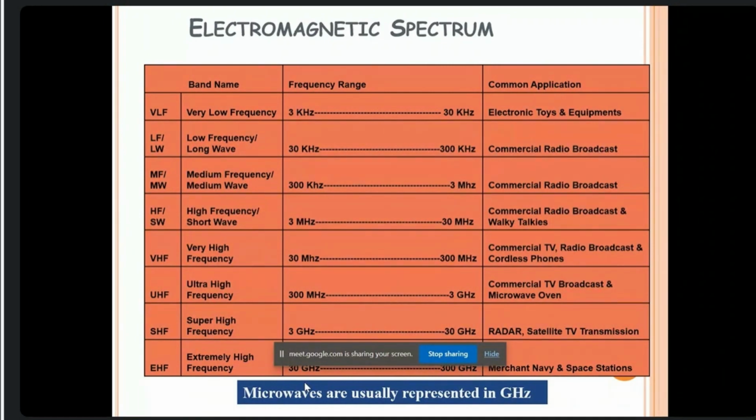cannot be used at higher frequencies because we have a transmission line problem. Whenever the wavelength and physical dimension become comparable, we have all the transmission line problems. That is, a simple resistor exhibits some series inductance, or the inductor exhibits some capacitance in between the coils. Even the capacitor leads exhibit some series resistance and also inductance. So these are all the problems in choosing the component.